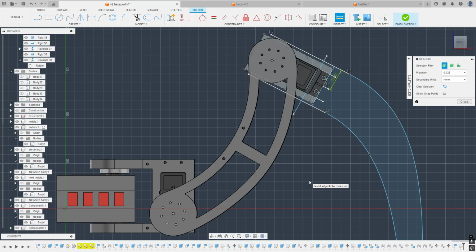Torque is force times distance. Okay, correct. 50. That's correct. So it can lift 3 kilograms, 6.6 pounds. That's an absolute max. So at absolute max, we have the arm reaching completely straight out, 50 millimeters plus the body length, which should be another 100 millimeters, assuming somewhere around there. 100, maybe a little bit more. Let's do 200 just to be safe.